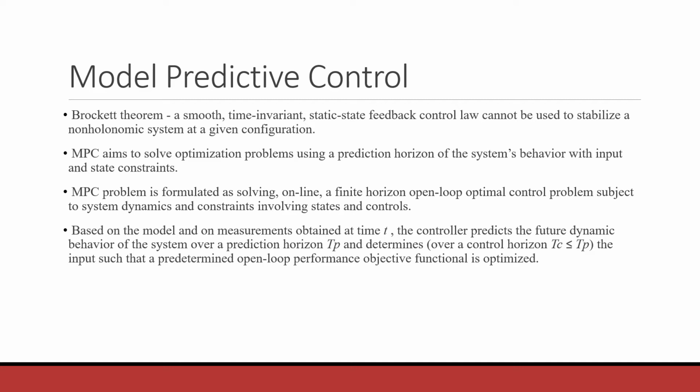The term MPC, also known as receding horizon predictive control (RHPC), does not designate a specific controller but rather an ample range of control methods that make explicit use of a model of the process to obtain the control signal by minimizing the cost function. The most important concepts appearing in the predictive control family are basically: first, explicit use of a model to predict the process output at future time instants; second, calculation of a control sequence minimizing a cost function; and third, a receding strategy, so that at each instant the horizon is displaced towards the future.